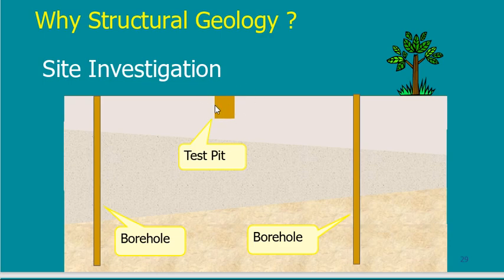Usually they don't give me important data about layering, but what gives me important data about layering is these deep boreholes. So I will drill one borehole here and another borehole here. I will get samples showing me that this is a layer, then I have another layer, then a third layer, and so on. Here layer 1, layer 2, layer 3.